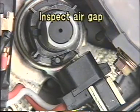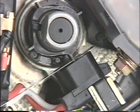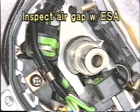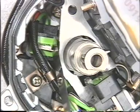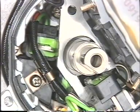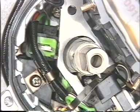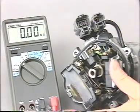To inspect the air gap with a non-magnetic feeler gauge, measure the gap between the signal rotor and the pickup coil projection. In the case of ESA, measure the gap between the NE signal pickup coil and the G signal pickup coil. Also measure signal generator resistance.